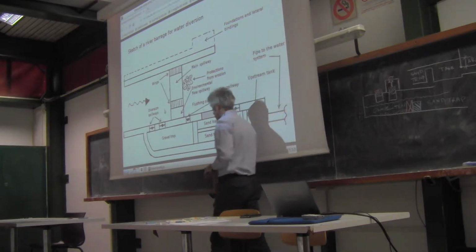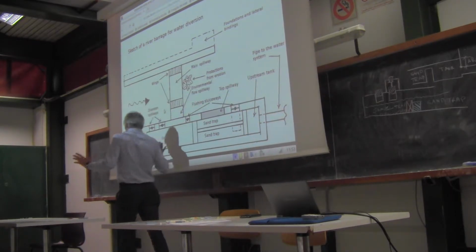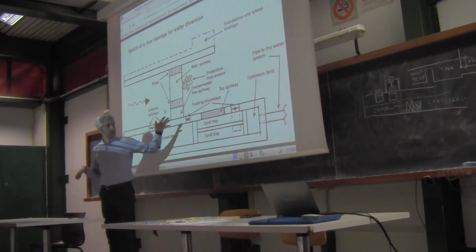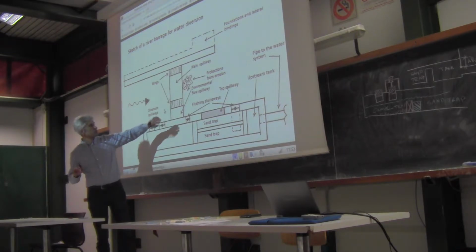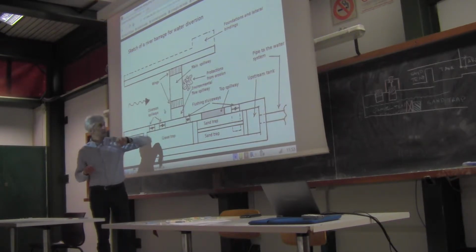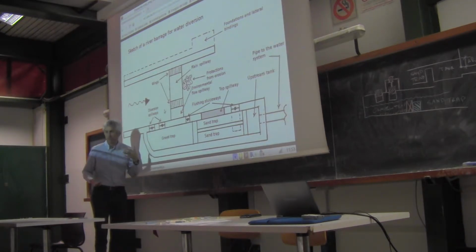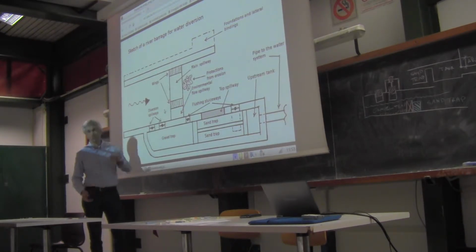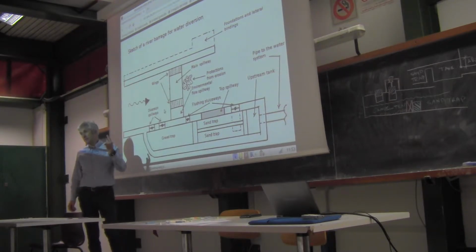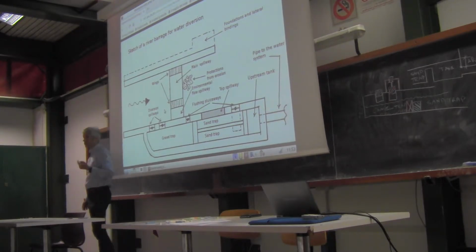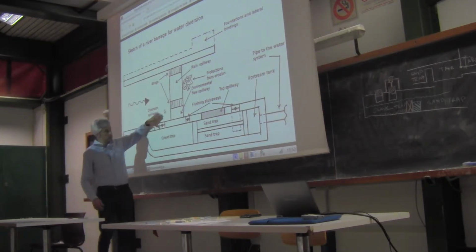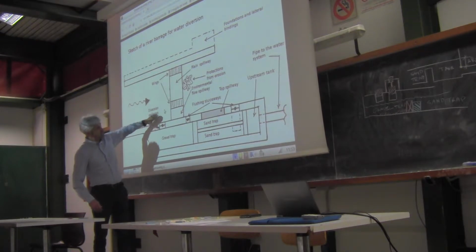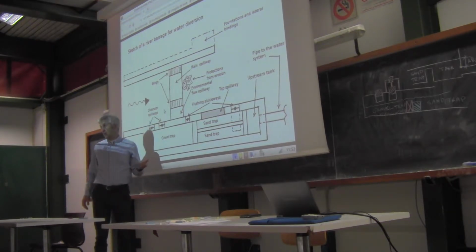Okay, so with these considerations, we fix the elevation of the environmental flow spillway. Okay, and then what is the difference in elevation between the environmental flow spillway and the diversion spillway? There is a fundamental requirement. We cannot get any water until the environmental flow passes through the environmental flow spillway.